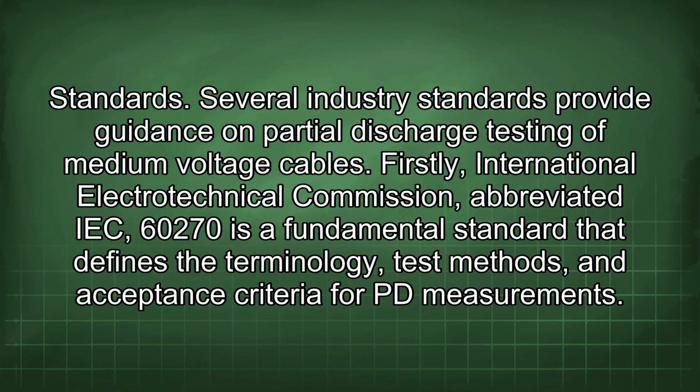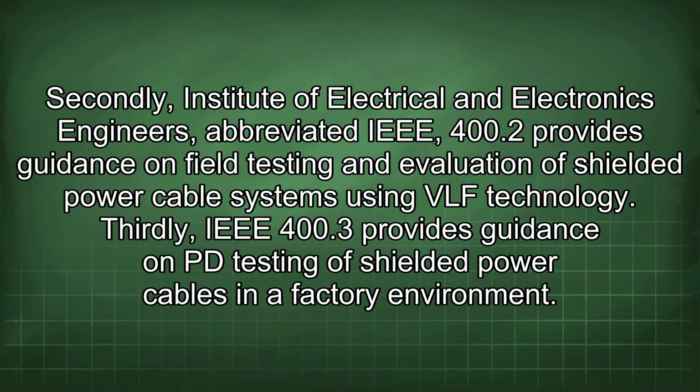Firstly, International Electrotechnical Commission, abbreviated IEC 60270, is a fundamental standard that defines the terminology, test methods, and acceptance criteria for PD measurements. Secondly, Institute of Electrical and Electronics Engineers, abbreviated IEEE 400.2, provides guidance on field testing and evaluation of shielded power cable systems using VLF technology. Thirdly, IEEE 400.3 provides guidance on PD testing of shielded power cables in a factory environment.